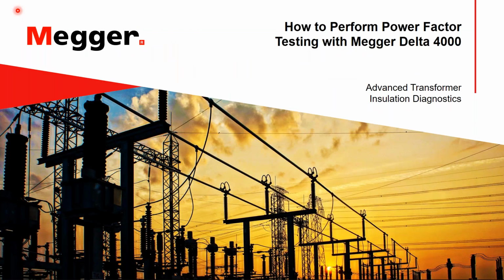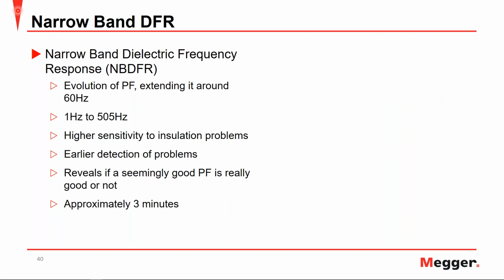So now that we've looked at the software for the Delta 4000, I want to go ahead and take a look at some of the advanced transformer insulation diagnostics at this point. First, we'll start with the narrowband dielectric frequency response. And narrowband dielectric frequency response is essentially an extension of the power factor around the 60 Hertz measurement.